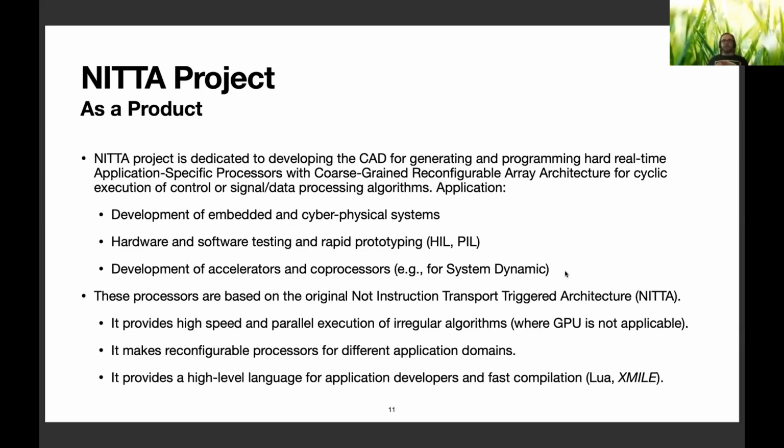For today, we have different approaches for how software developers can develop hardware. And usually it can be separated into two groups. It's high-level synthesis, which allows us to directly write software in, for example, C, and usually it is the C language, and translate it into hardware and use it. But usually it's not a normal C programming language. It is a very special subset of C with additional pragmas to instruct the tool how to synthesize the target hardware.